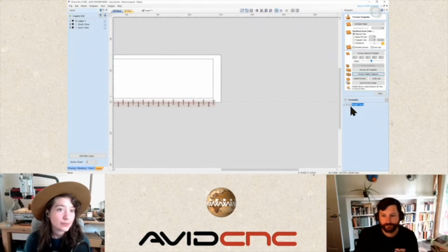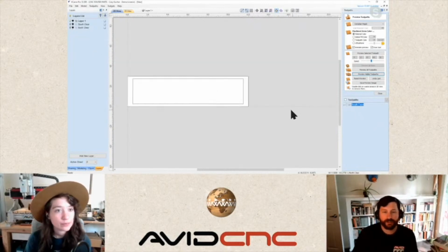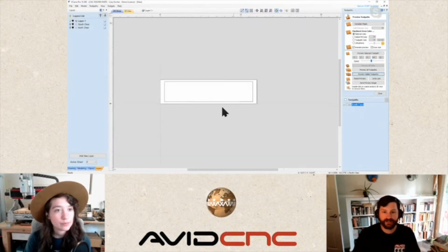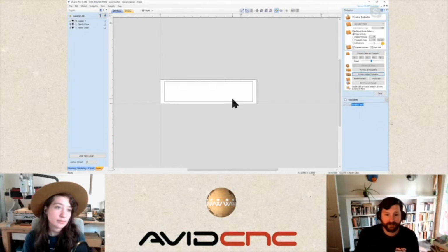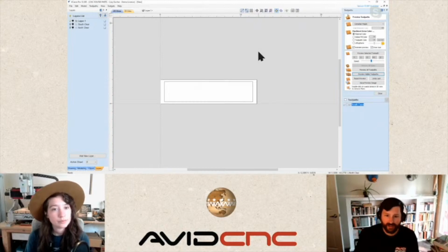So let's imagine that we were holding this in a vise on the right and left sides, and we've faced the south and north sides of our material, and now we want to come back and take care of the east and west. So we might use some additional work holding from the north and south side of our material, and that way we can work on this, engaging it from the side of our material away from our clamps.